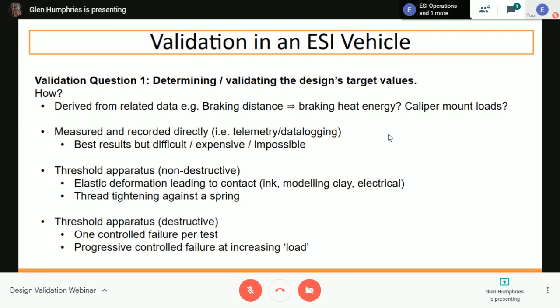And the spring can be replaced with other springs of different stiffness or different preload. So the link is preloaded to stay at its extended length until it sees a load of 300 newtons or 3 kilonewtons, whatever the figure may be. And then it compresses slightly and closes the contact.